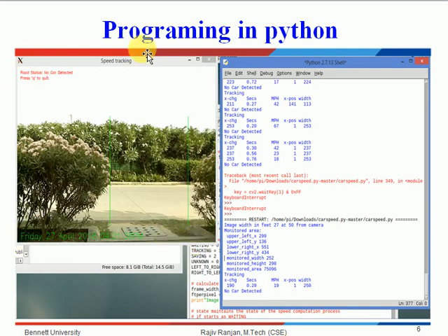The first thing we have to do is create a monitoring zone by dragging the mouse over this window and pressing C. After pressing C, it will generate two imaginary lines on the roadside, which will be the entering and exit points of the vehicle from either side.